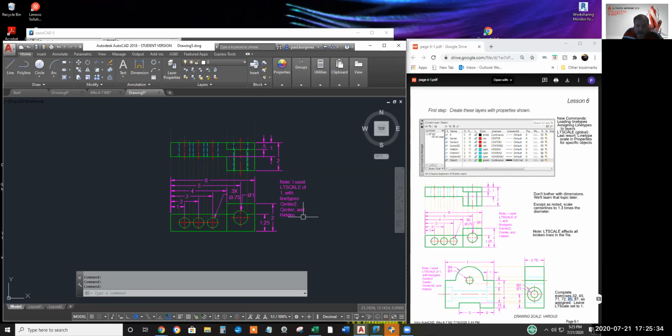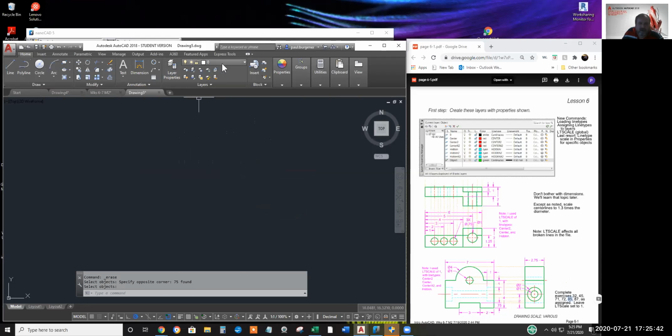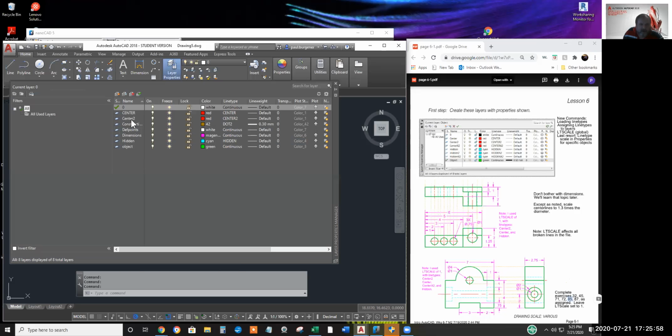Thank you. You're welcome. So we'll erase everything. I don't believe I can use anything. Maybe the text. And we do have a hidden layer, and we do have a center layer. Later, we can purge out the center 2 layer with the purge command. I believe you can delete it manually from the dialog box too. Let's find out. Click delete layer, and if there's nothing on the layer, you can delete it. I'll leave construction, may or may not use it.